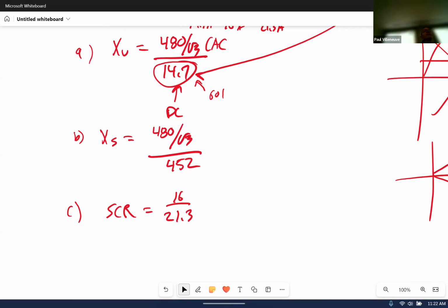Questions? This was definitely new material. But my concern is that so many of you still did the AC voltage divided by DC current. What that leads me to believe is that you don't fully understand where that DC current is going. And I know we just had a lab yesterday, and unfortunately, because we missed two Mondays, we're a little bit behind on labs, but hopefully you're starting to see this DC current goes into this winding that rotates around. It has nothing to do with the AC output.